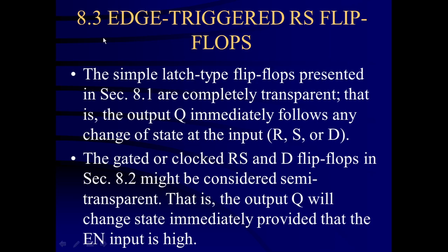So we'll be starting with the edge-triggered RS flip-flop. The simple latch type flip-flops presented in section 8.1 are completely transparent. That is, the output Q immediately follows any change of state at the input, that is R, S or a D flip-flop.